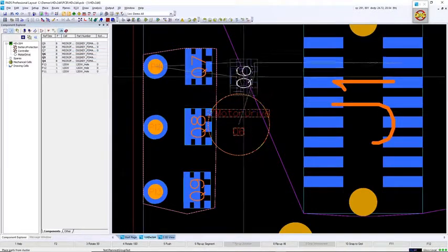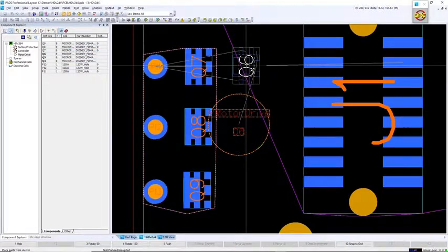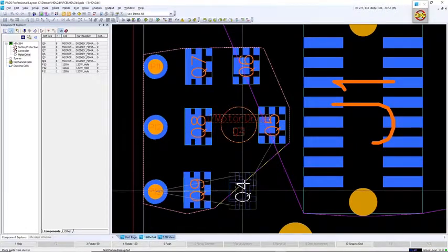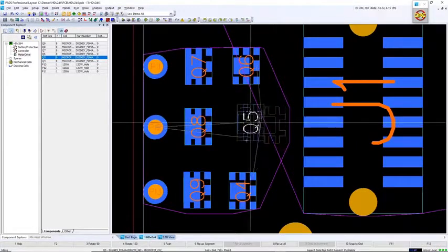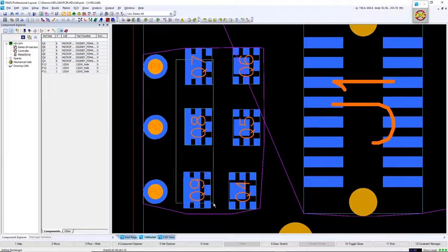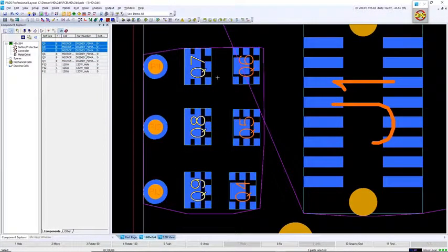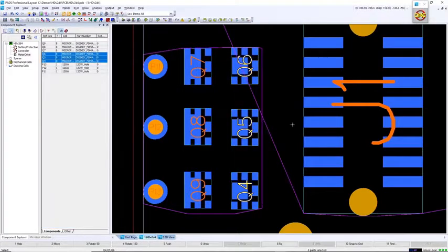From there, I can pull out the individual FETs and place them in their proper location. To assist with the placement of these FETs, I'm going to use a vertical alignment feature for each column of parts to make sure they're perfectly lined up. Lastly, before we move on to more 3D MCAD collaboration, we're going to go ahead and place this PIC controller.